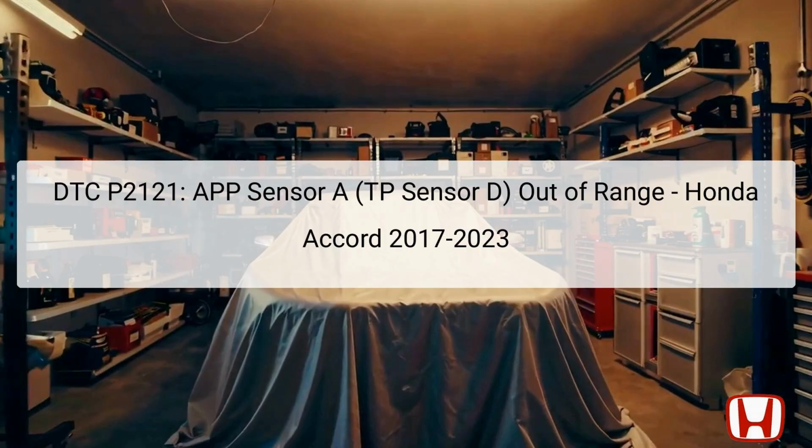It is located in the lower dash area, directly connected to the accelerator pedal module. This sensor communicates with the powertrain control module, PCM, which interprets the data to manage engine performance and throttle response. When the APP sensor signal is in an abnormal state, it can lead to poor engine performance or even safety concerns, making it essential to address this DTC promptly.